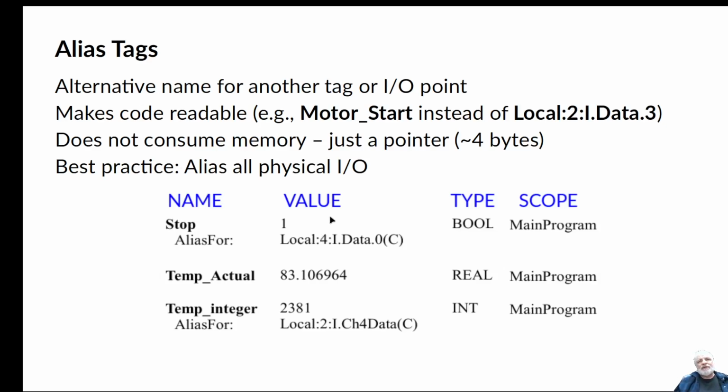And then I stands for input. And then data.0 means 1 bit. So this is 1 bit, which is type Boolean or bit. And then you also have the scope. So you can actually have multiple programs. You can have what they normally call the main program, and then you could create other programs which would most likely be sub-programs to the main program. And so you can have scope of where these tags are accessible, for what programs can access it.